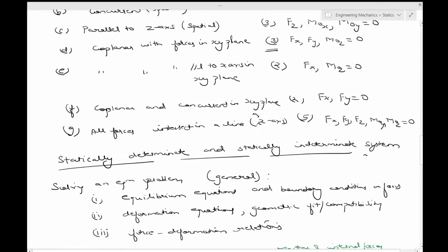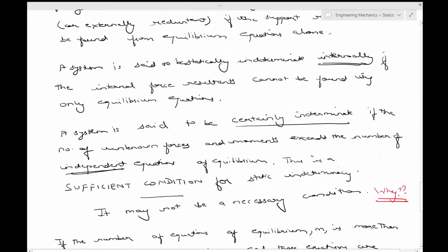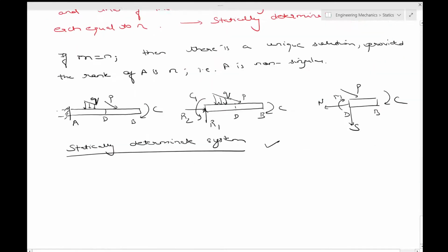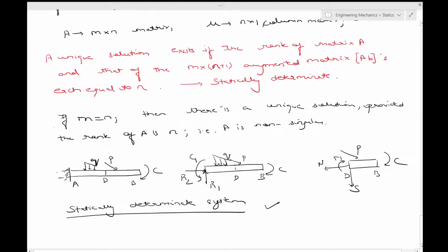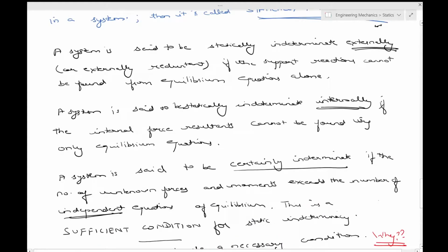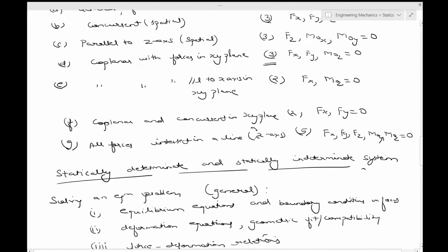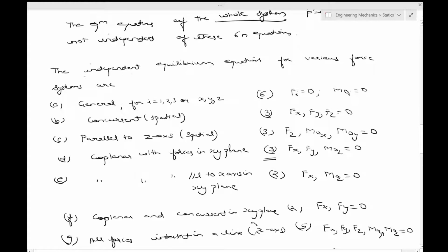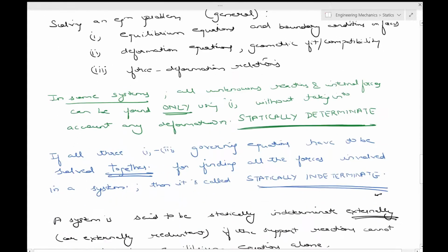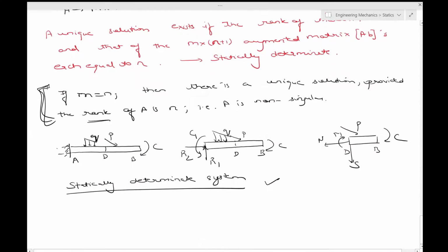So that's why it's statically determinate, provided this condition is satisfied. And anyway, the rank counts the independent equations, because these are the independent equilibrium equations. The fact that rank already considers independence, so just don't count it. It should also be independent.